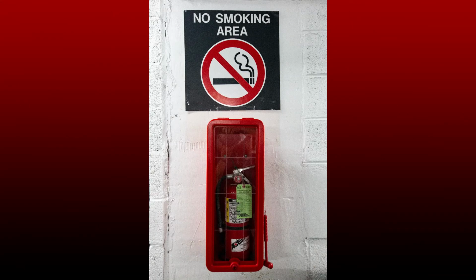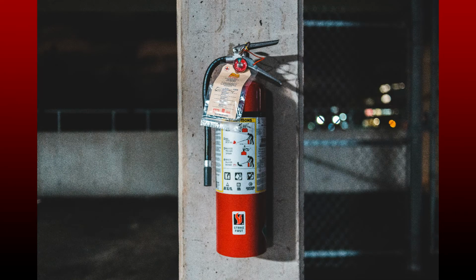So let's talk about inspection and placement of portable extinguishers. Now, NFPA 10 outlines the minimum inspection, testing, and maintenance for fire extinguishers. The visual inspection ensures proper extinguisher placement. Proper placement ensures that extinguishers are visible and accessible in a normal path of exit travel. The extinguisher placed should be the proper type and rating for the potential hazard.